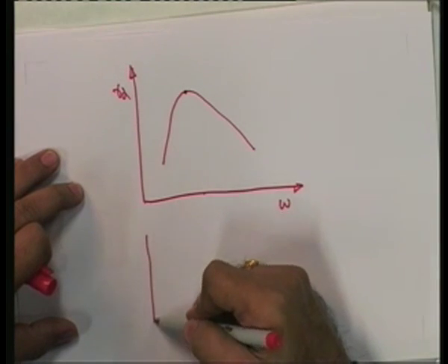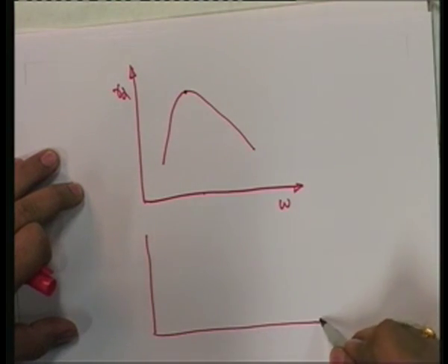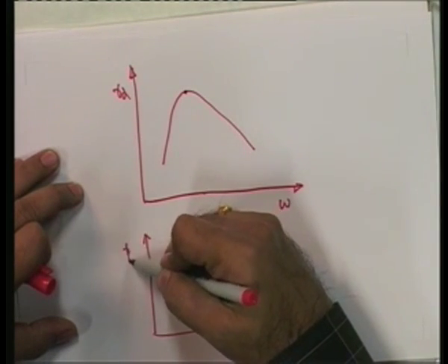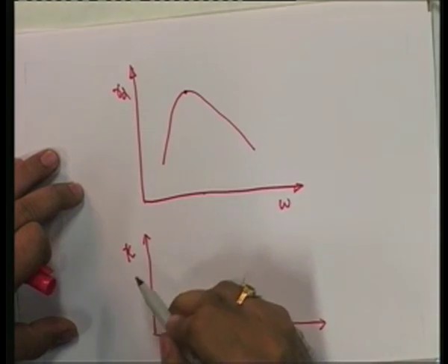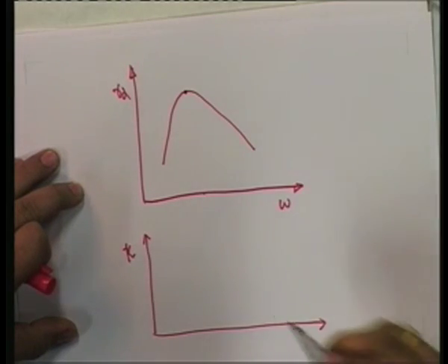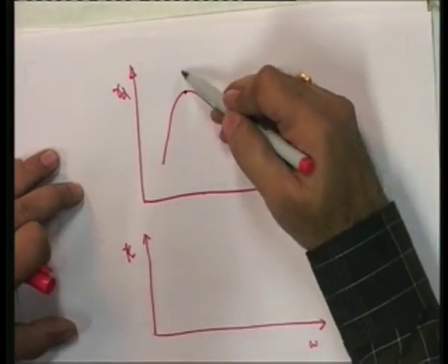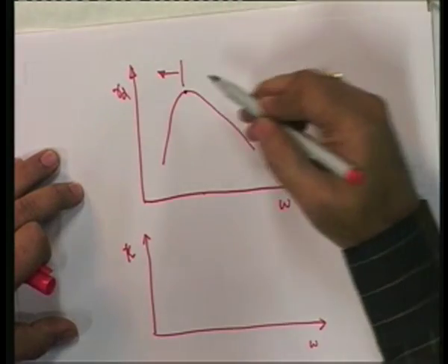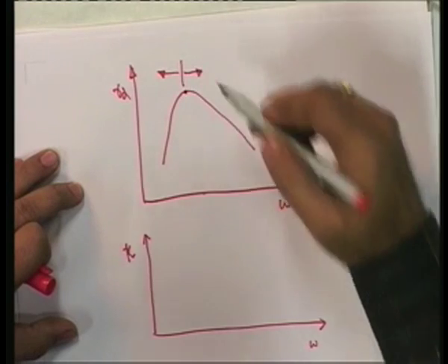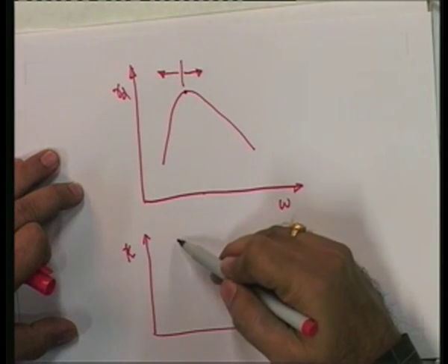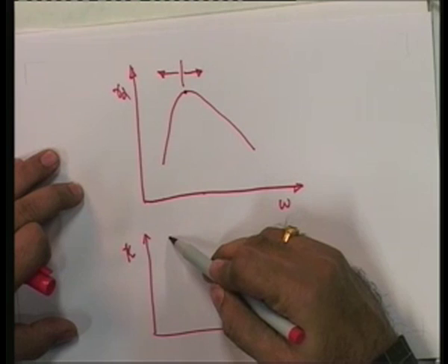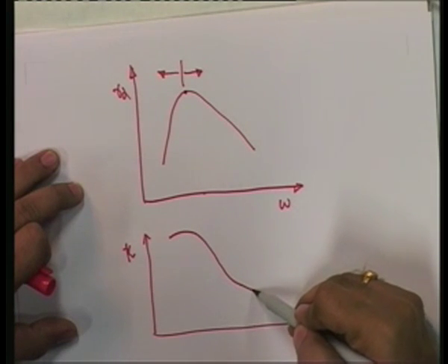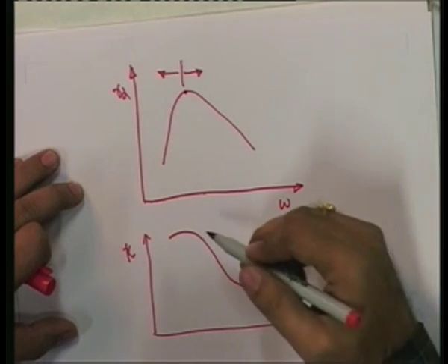If you plot the permeability value K, in meters per second, against water content, this side is the dry side of optimum and this is the wet side of optimum. Here, on the dry side of optimum the soil can have high permeability, and the permeability value decreases for a given typical soil.